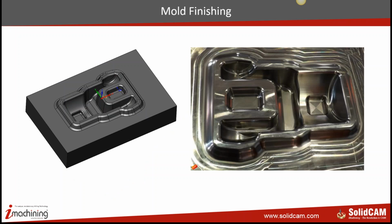Another example was this mold finishing. You can see on the right-hand side the finish that was achieved with HSS. The entire mold was finished using HSS. Each surface, each fillet was picked up individually and machined. Even the merging between that fillet and the other surface was nicely done.